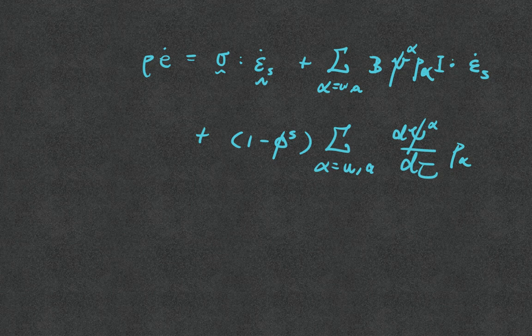There is a solid, so in the void space there is air and water, and by the relative pressure that they inject into the void space, it would lead to the change of the degree of saturation. Okay, more water, more air, less air. And then there's another term coming from the previous gigantic term from the convections that is related to the M alpha times the P alpha. I won't write down the details just for simplicity.